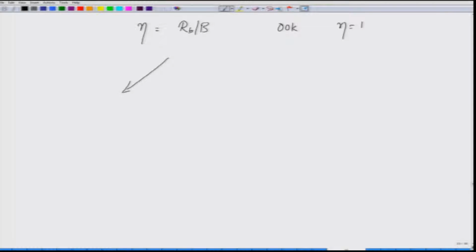To increase the spectral efficiency, there are two major approaches. One is to use what are called single carrier systems, but use higher order modulation. Okay. With higher order modulation, your basic modulation formats start with say 4 PSK, a QPSK, or 8 ARY PSK, or 8 PSK for short.